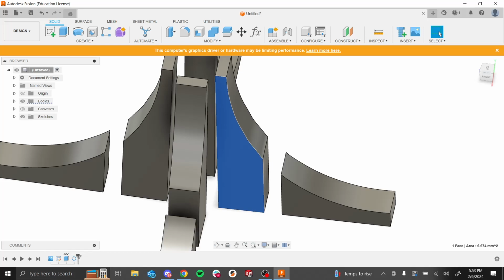So again, I'm showing you some kind of unorthodox techniques right now, just to show that you can go back and change things, right? So normally if I was doing this, I wouldn't do the circular pattern right now, but you can do it, but you can also go back and change it. So over here on the bar on your timeline, you can move it back and forth to hide and show certain processes that you've used. So in this case, I kind of want to hide the circular pattern, and then I'm going to add it back later.